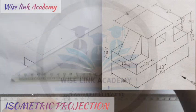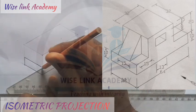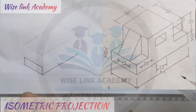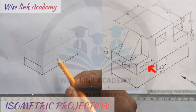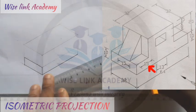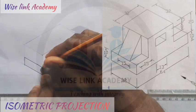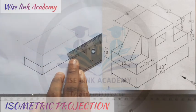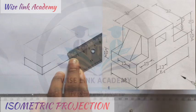Next task is that you take your set square this way. This edge here, you draw it down here with a faint line. Observe from here to somewhere here is going to be 15. So measure out 15, which is this, and it's taken. Also, here too, I'll have 15 at this section, right?